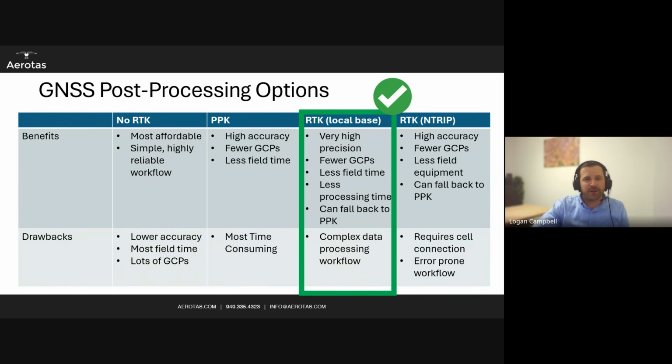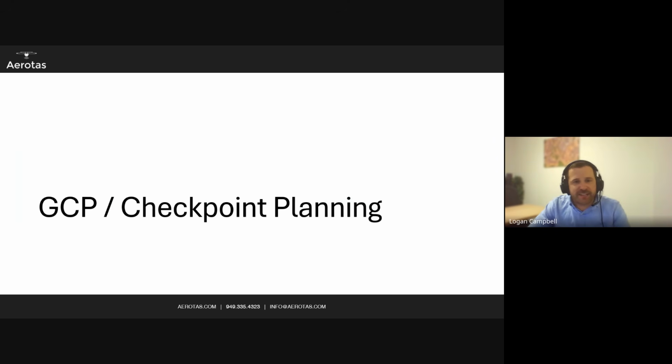We've seen all sorts of different edge cases here, whether you set your GPS system in a place that might have some sort of building shadow or multipathing or whatever it is. It allows for real-time correction of errors in the field. So that's enough for RTK setup for right now.